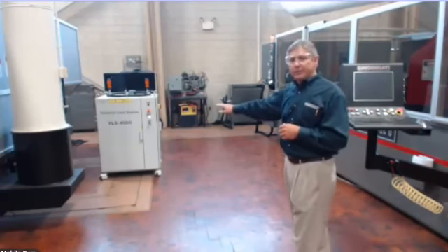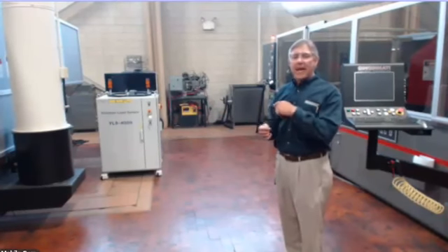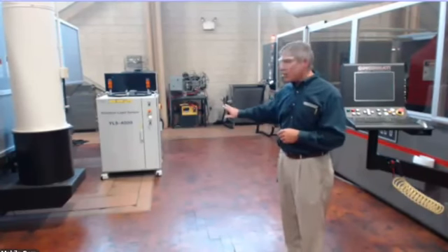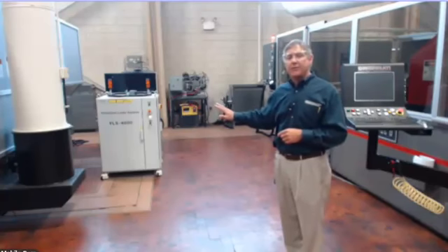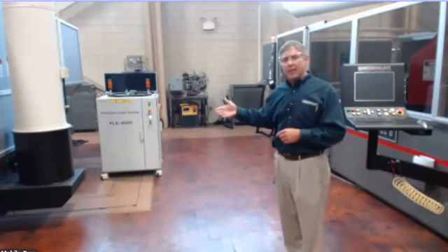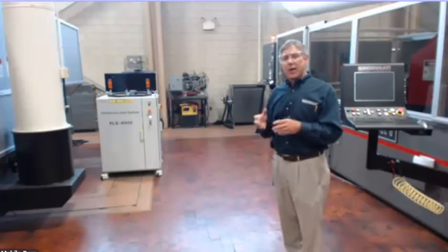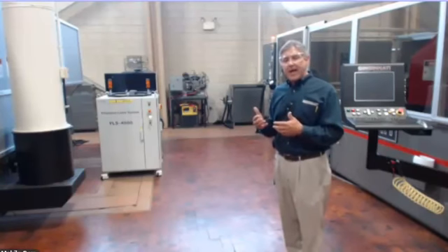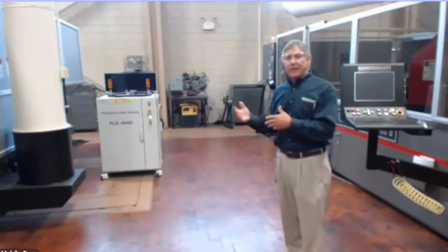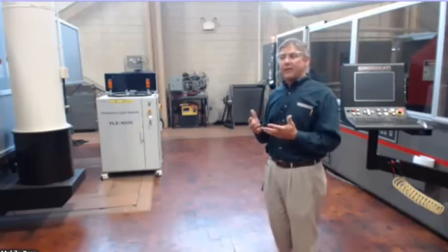On the fiber laser, it's a little simpler system here in that instead of having the glass tubes and the gas circulating through that, they're all solid state laser mediums here, and that is a glass fiber that's doped with an element called ytterbium. Instead of high electrical voltage directly to a gas or to that medium, what we do there is we hit it with very high intensity flash lamps, and that's what excites the ytterbium atoms in that glass and creates the laser beam.